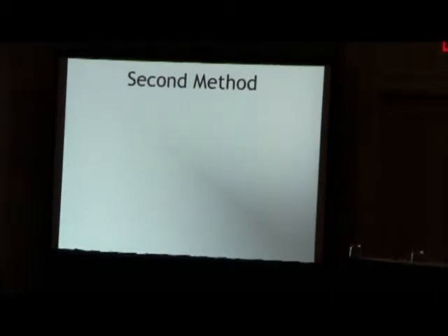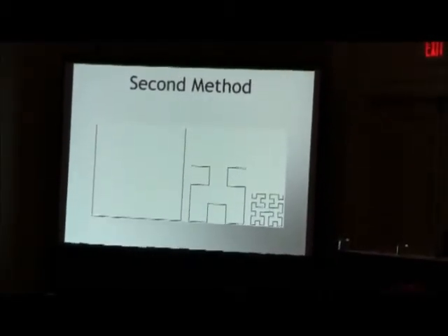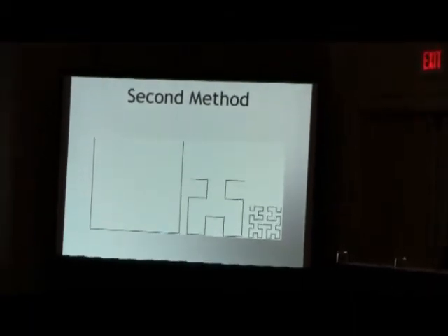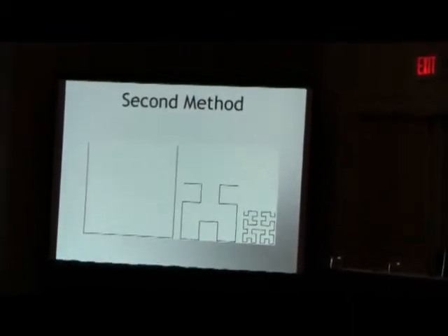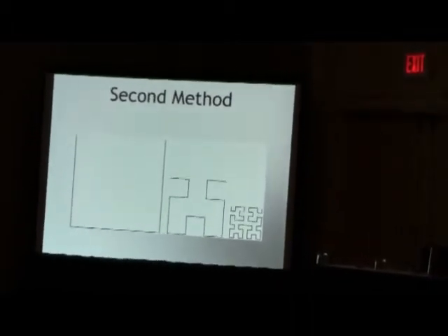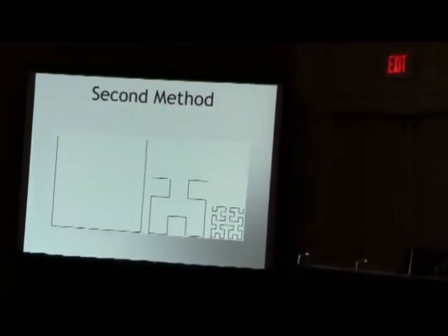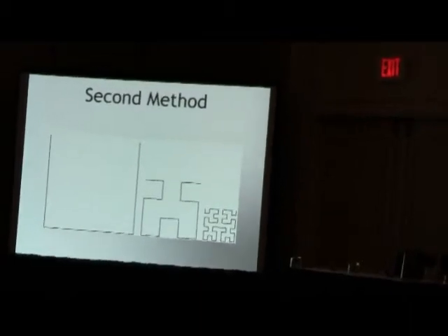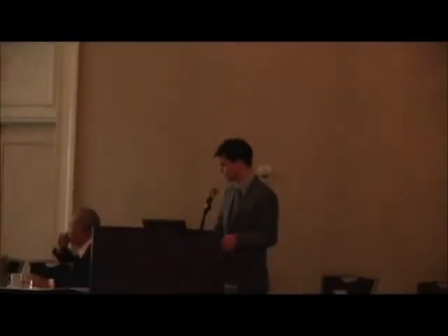Now, whereas before in the first method, you maintain the same overall size or area of your fractal antenna, in the second method, you maintain the same overall perimeter length of your fractal antenna, so that after each iteration, you shrink the overall size of your fractal antenna after each cycle. So you can easily see why either of these two methods would be favorable in designing antennas.